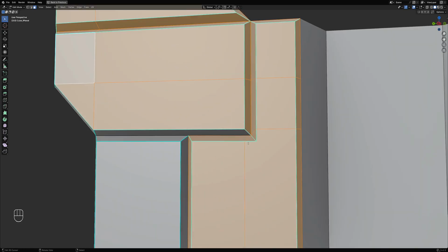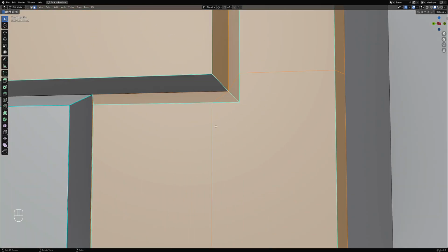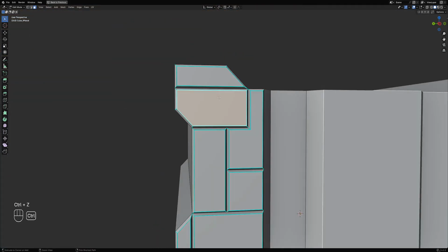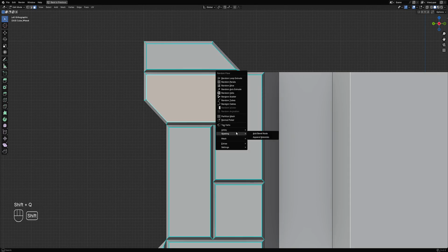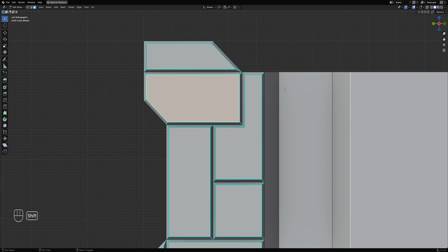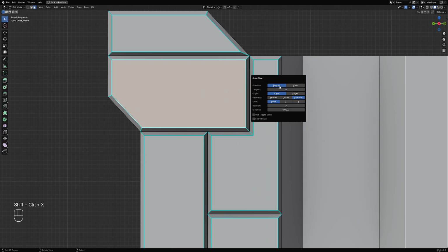Okay, and you can see here that this is not supposed to cut that way. So, quad slice. It's in Random Flow. If you only have Random Flow, it's in the mesh submenu. Quad slice, and then let's get the right tangent, linked. So for this one, linked only.